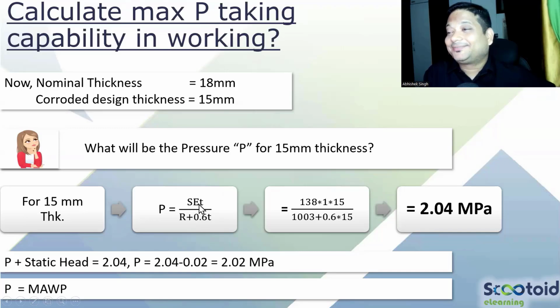What about radius? Radius will be 1000. I just told, right? It's very new. So it has not corroded. So why would your radius change? It won't change, right? It's new. So just apply the logic. If you have just made it, your thickness is as it is. It has not corroded. So your radius will also not change. So your radius will be 1000. Thickness 18. Give me the value. So most of you have got 2.45. So clear?